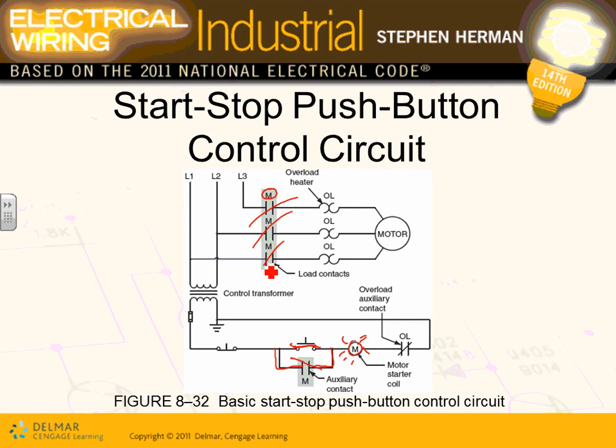When Adam comes and gets mad and he wants to open this, you push the stop button. Now this is de-energized. Now this will open, and each one of these will open. The equipment will stop functioning. We test these for master electricians in Minnesota. If you don't know this diagram and how to read it, you basically don't know control.